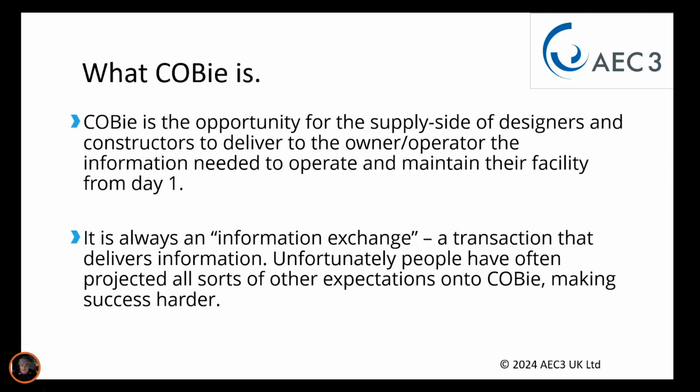It's always an information exchange. That's what the IE in the name stands for. It's a transaction that delivers information. And I think one of the misunderstandings about COBie has been to try and think of it as an application. It is not an application for facility management. It's not an application for building design and construction. It is a vehicle for getting the information from A to B at that handover moment.